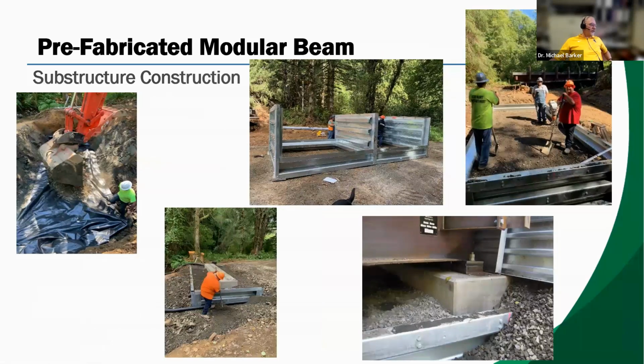And I just want to show some pictures of them building that bin, right? Top left picture, hey, you dig a hole. Middle picture, top, you build it. To the right, you start filling it and putting in the gravel layers with the geosynthetics in between. I forget what they were, 16-inch layers if I remember right. Put a sill on the top with the bottom left picture, and all of a sudden you've got a strong abutment that did not take big equipment, did not take concrete pours to do out in the middle of nowhere.